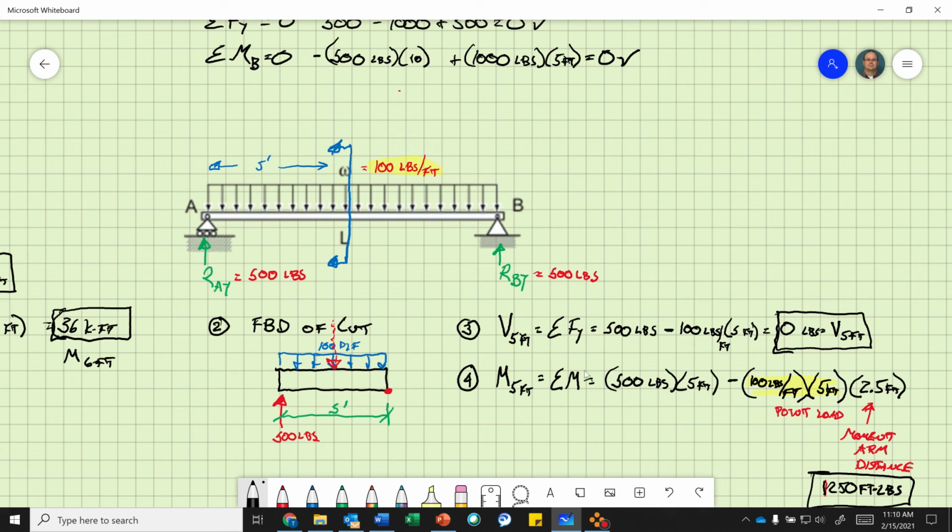So that's how you calculate shear and moments about any point. You could have something you want to hang from your joist or your ceiling rafters, and I need to know what that shear and moment is at that point and see what that extra load is. But now to size the beams, we need to find the maximum shear and the maximum moment, positive or negative. I'm looking for that magnitude, but I don't want to have to cut that beam every foot to figure out where that is. So I'm going to do a shear and moment diagram. Okay, and that is our next topic.